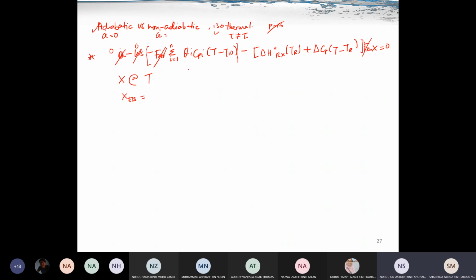We have two terms: conversion from the mass balance, or what we call conversion of equilibrium, and another term, X EB. The former we usually derive from the design equation, so it can be from reversible or non-reversible reactions, and also depends on the type of reactor, whether it is a CSTR or PFR and so on. X EB is the one that you derive from the energy balance.